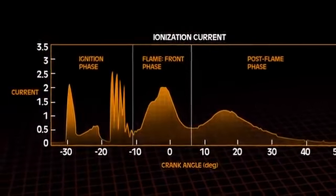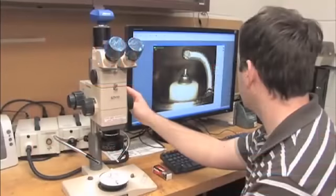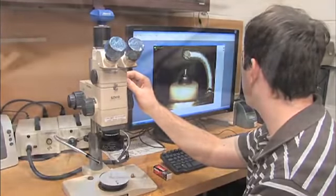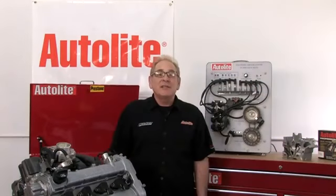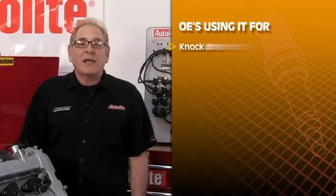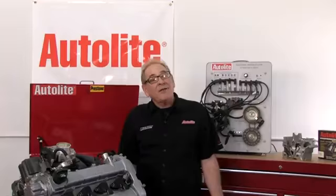This is complex stuff. What do the automakers use it for? Well, Autolite engineers use it for pre-ignition detection during initial engine calibration mapping. Saab first used ion sensing in 1988 for cam phase sensing and still uses it for knock detection. Many OEs are using it for knock and misfire detection as well. What other potential does it have?